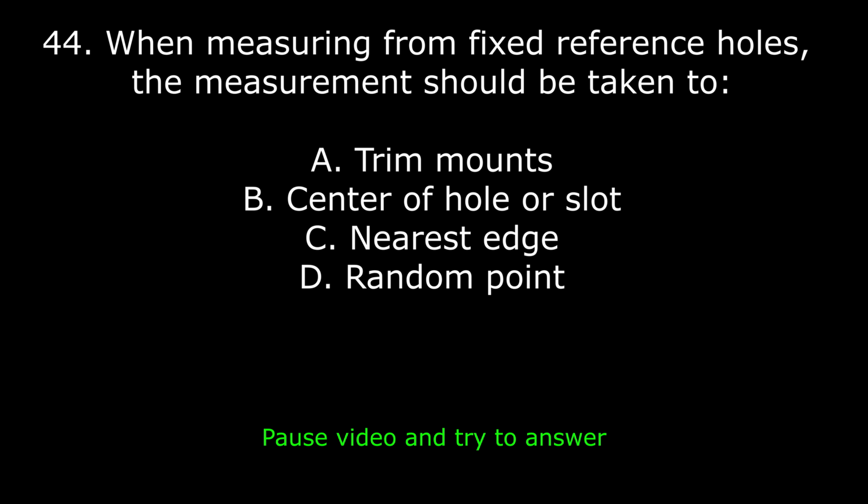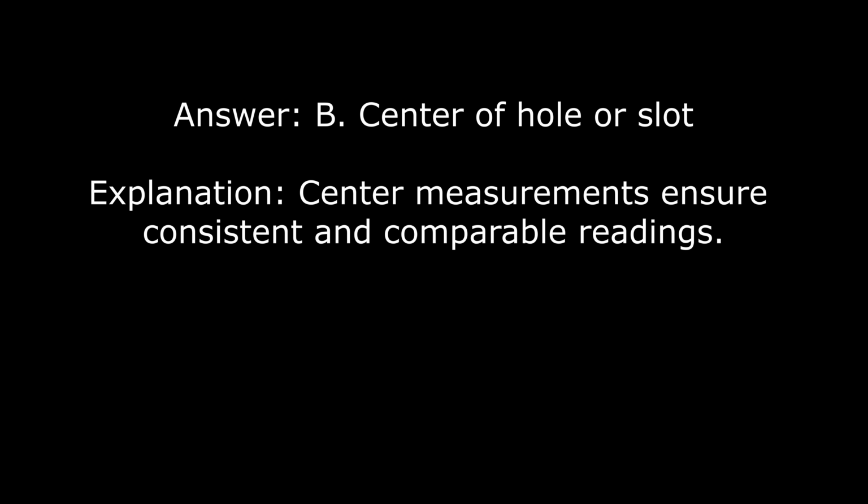44. When measuring from fixed reference holes, the measurement should be taken to A. Trim mounts. B. Center of hole or slot. C. Nearest edge. D. Random point. Answer: B. Center of hole or slot. Explanation: center measurements ensure consistent and comparable readings.